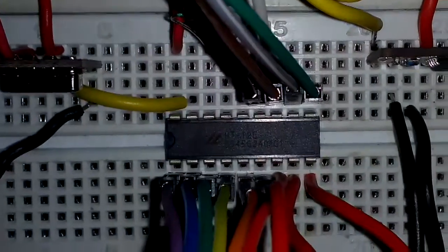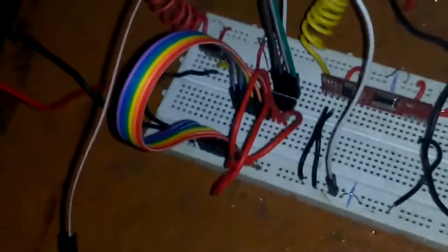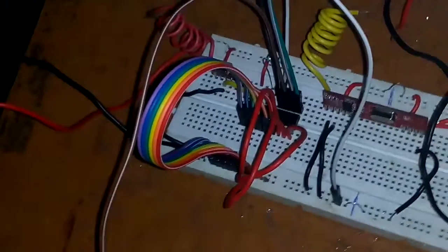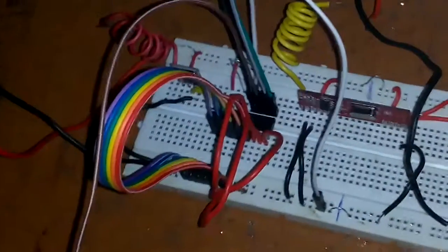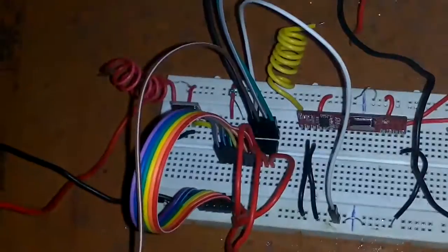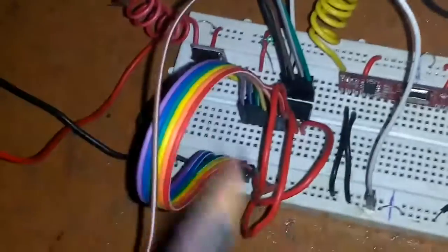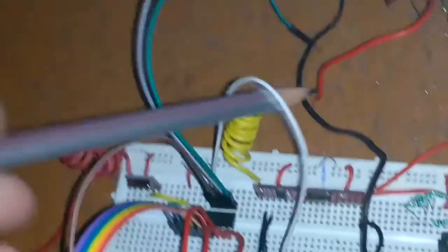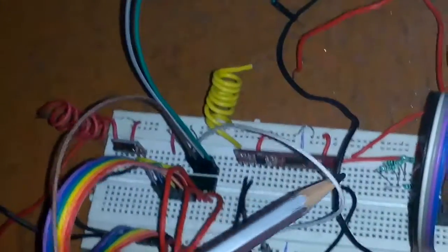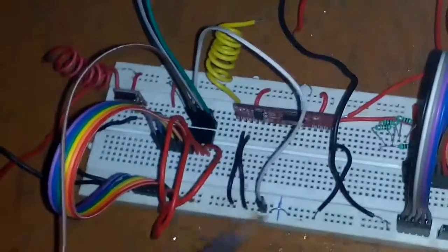This is our HT12E encoder IC. As I explained earlier, the encoder IC is nothing but a parallel to serial converter. We have only one antenna for that purpose, so we are encoding into serial data. So the working is like that. These are the 4 data pins. This is a transmitter enable pin. We must ground it to enable transmission, for transmitting the data.